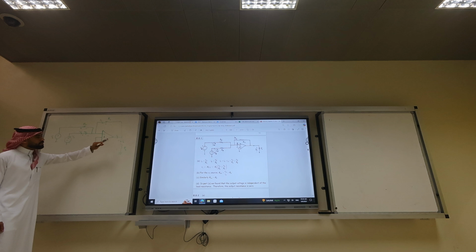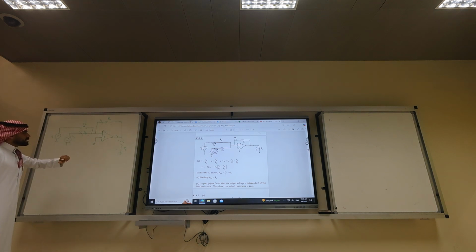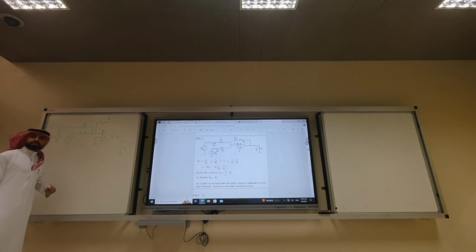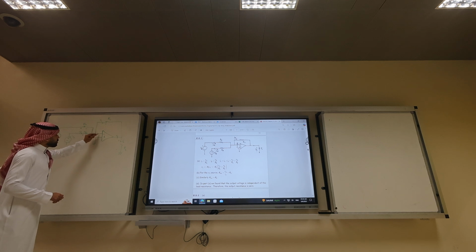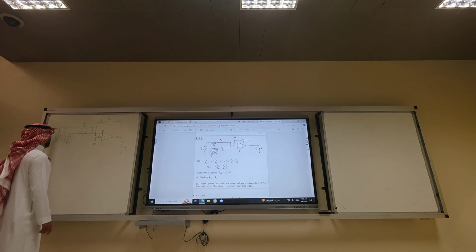So step number one, verify that there is a negative feedback. That's correct. Step number two, what was it? The virtual ground. So we have here a virtual ground, or the voltage drop between the positive and negative is zero. Call this Vx, okay? So what is IA?